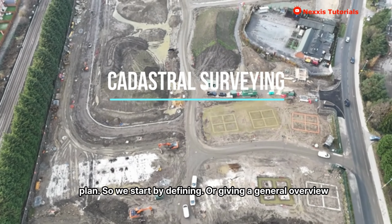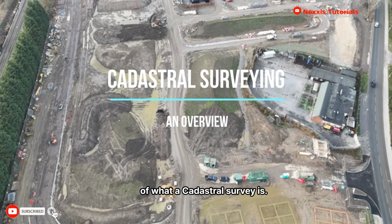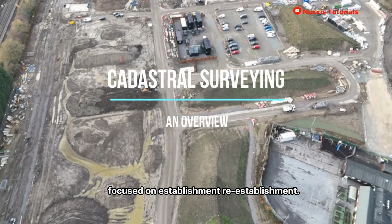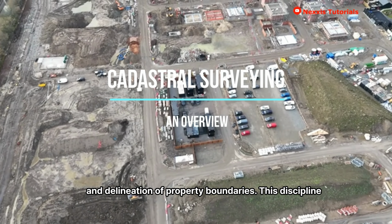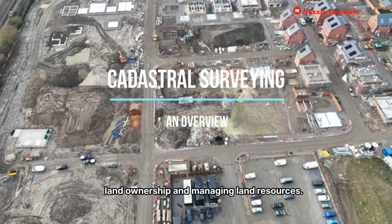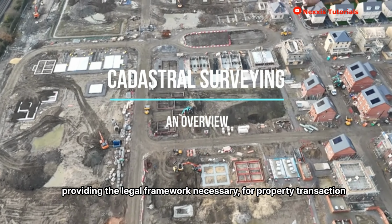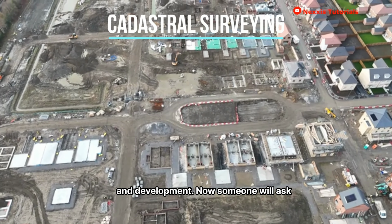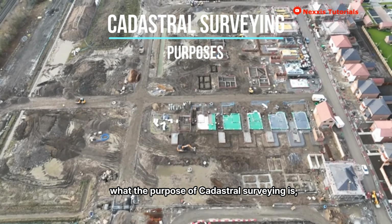So we start by giving a general overview of what a cadastral survey is. Cadastral surveying is a specialized field of land surveying focused on establishment, re-establishment, and delineation of property boundaries. This discipline plays a crucial role in defining land ownership and managing land resources, providing the legal framework necessary for property transaction and development. Now, someone will ask, what is the purpose of cadastral surveying?